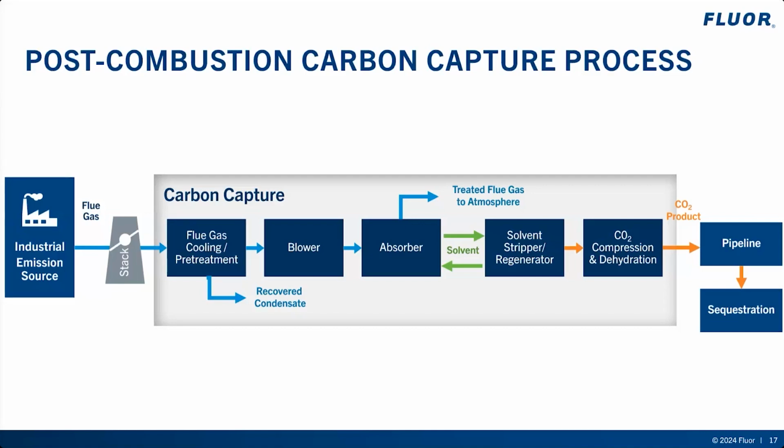The fourth and final step is CO2 compression and dehydration to meet final CO2 product specifications. The CO2 compressor is a multi-stage machine that is typically divided into a wet and dry section. The wet section includes intercoolers and interstage separators between compression stages to collect any condensed water. At an intermediate pressure, the CO2 product is sent to the dehydration unit to remove residual water from the CO2 and meet final product specifications.